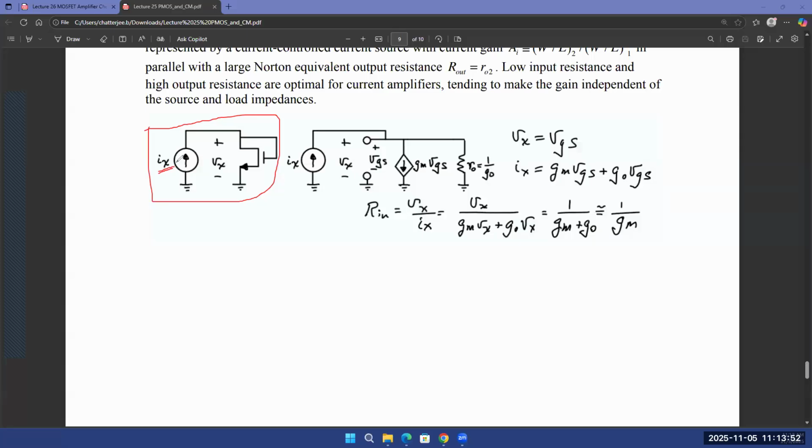And when you are doing DC analysis, again, you can get rid of all the AC quantities, because if you're doing a DC analysis, AC does not matter. Eventually, the circuit is a combination of both the AC and DC. So they are superimposed on top of each other, but the beauty of the superposition principle is that you can analyze the current sources or voltage sources separately. So your DC analysis could be separate from your AC analysis, just to make your life simpler, but both of them happen at the same time, even though you can analyze them separately.